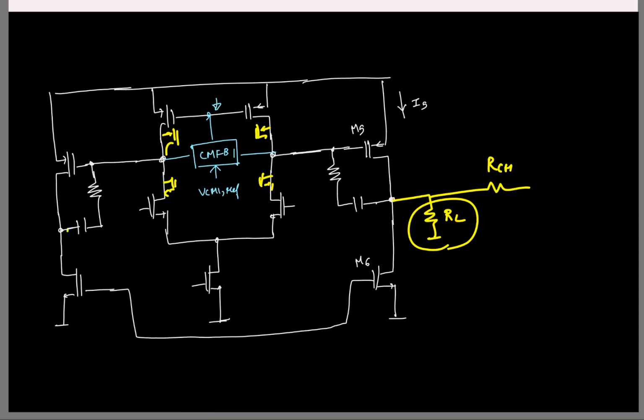In that case, the output impedance is going to be really large, so it might not be practical to have a common mode resistor larger than this output resistance. Whereas here I know that the second stage is going to have a modest gain, so I can use a resistive common mode detection here. Okay, so let me do that then.